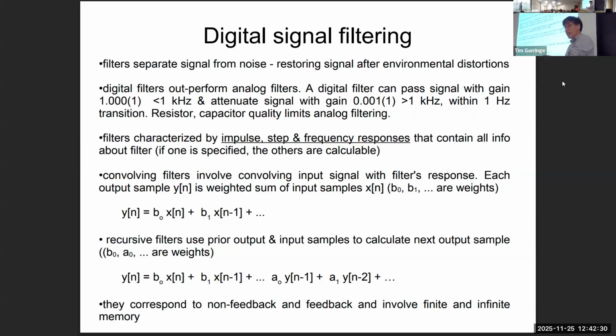And then we're going to represent the output by the variable y. So y[n+1], y[n+2] would be a series of outputs. And we can write for the convolving filter the output value of a particular sample, say the nth sample, in terms of the input values up to that nth sample by this little convolving filter equation here.